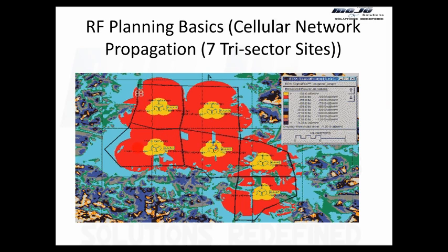Is it the only job? No. Does it only do that? No. Because I'm telling you the signal strength, but the planning tools which we have also tell you the quality. For UMTS, quality means Ec/Io. It tells you what Ec/Io you should expect in a given zone, and gives you similar plots for Ec/Io. For LTE, it's SINR, and it gives you similar plots for SINR. In LTE we also use RSRQ. We will discuss that in the slides to come.